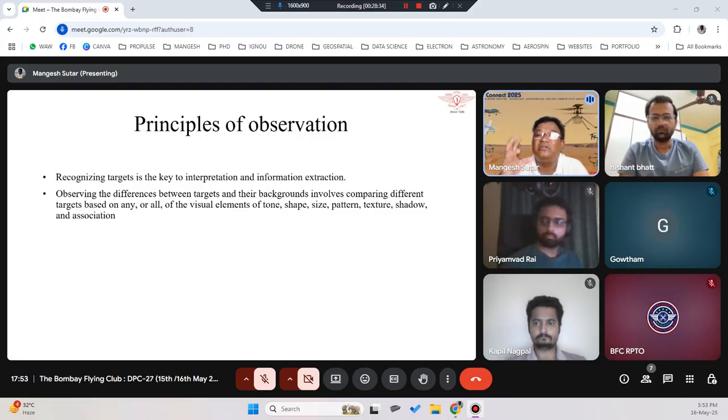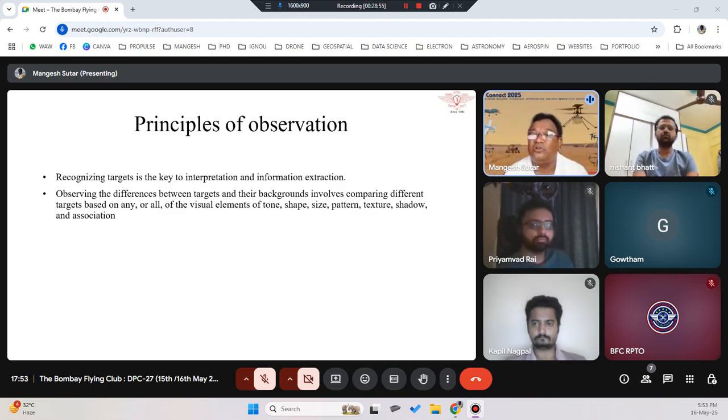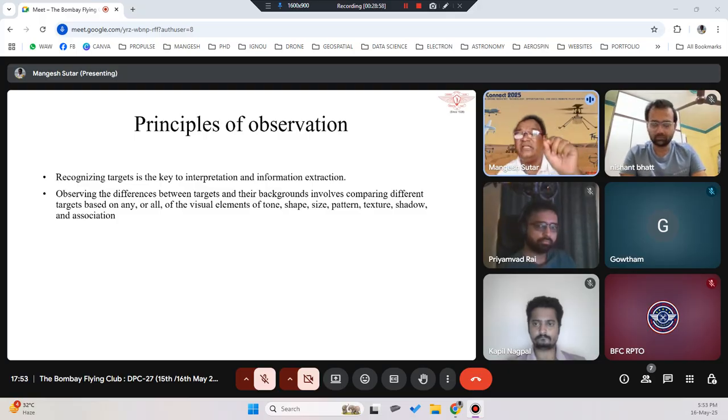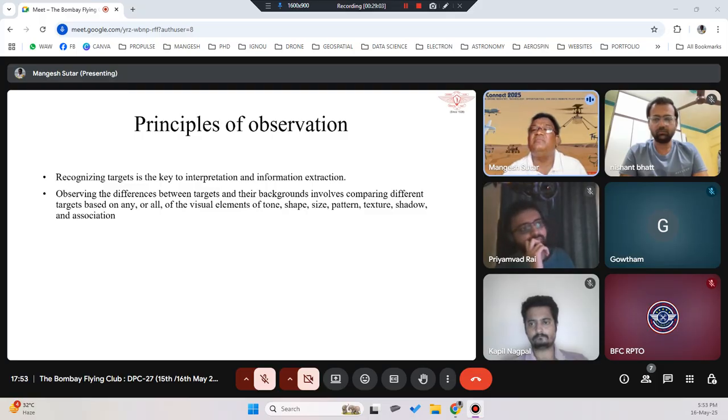Then we asked them to capture the insulators and the joints. As the tower becomes smaller on top, there are a lot of joints, a lot of connectors, a lot of bolts. At any joint location, a member bar has to be there. If that is missing, broken, or not put in during installation itself, or any bolt is missing, you need to capture it. A lot of times you are supposed to put 3 bolts, but the person who makes the tower just puts 2 bolts only. You are supposed to put the third bolt also, so that bolt is missing. Your drone should capture those images.